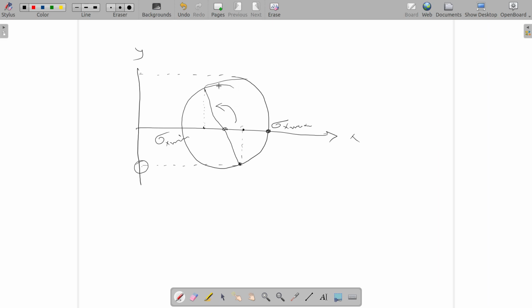And you also have a plane where the maximum value of shear stress is acting, but remember that that's not the definition of principal plane. Principal planes are the planes on which maximum and minimum values of normal stresses occur, and they are usually separated by an angle of 90 degrees in the 2D case.